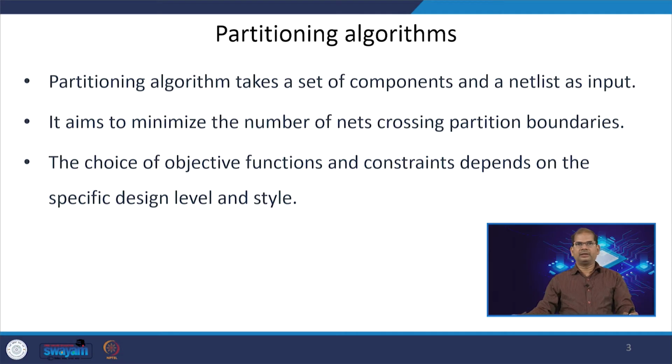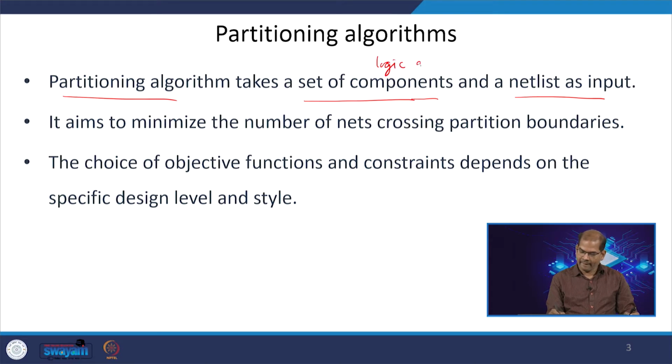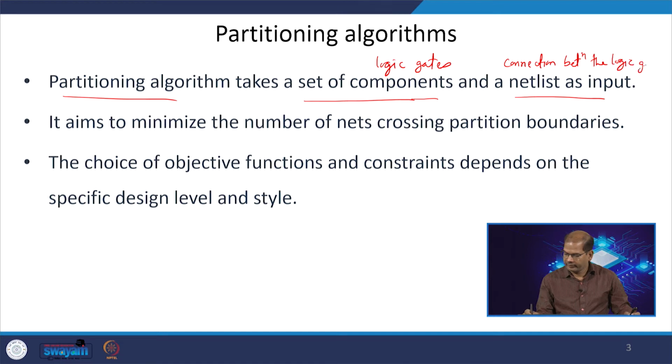So, what is a partition algorithm? A partition algorithm is a type of algorithm that takes some inputs and produces some output. It takes the set of components and the netlist as input. The components are basically the logic gates, and the netlist is basically the connection between the logic gates. So, this is the input to your partitioning algorithm.